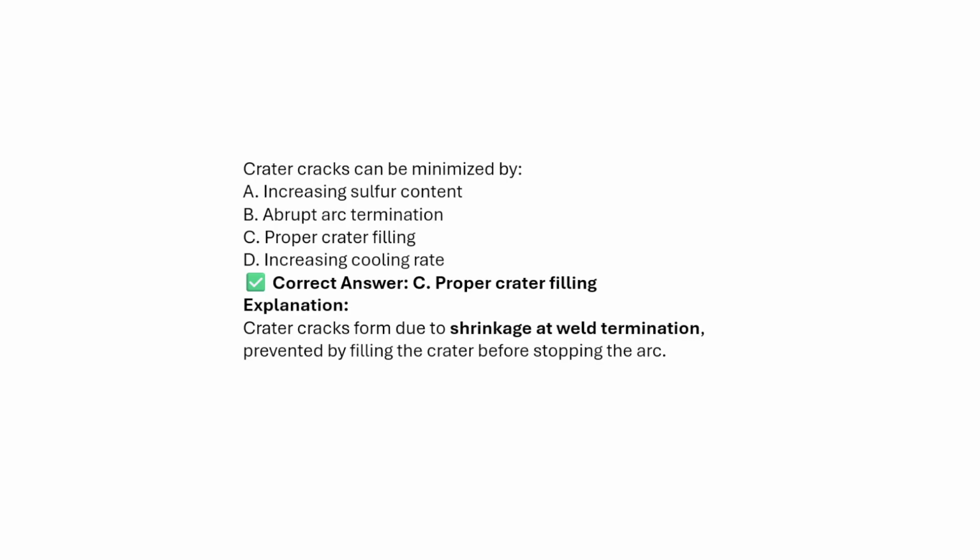B, abrupt arc termination. If we stop the arc suddenly, that is also not the way to prevent cracking. That will create the crack, followed by faster cooling, which results in cracks. C, proper crater filling. If a crater forms and we fill it with material, yes, that could be the reason.